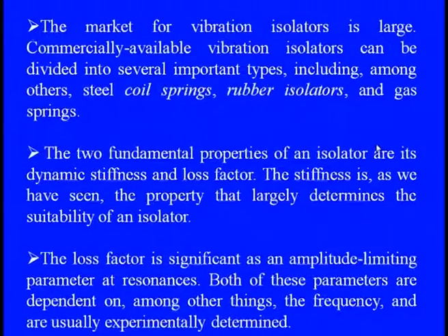Second, the loss factor. It is a significant amplitude-limiting parameter at resonance. Both parameters, the stiffness and the loss factor, the dynamic stiffness we should say, because it is under vibrating conditions, are dependent on various other things like the excitation frequency and the amplitude, and we need to find them out experimentally.